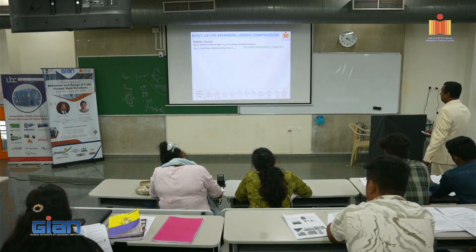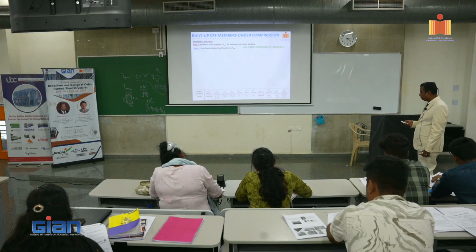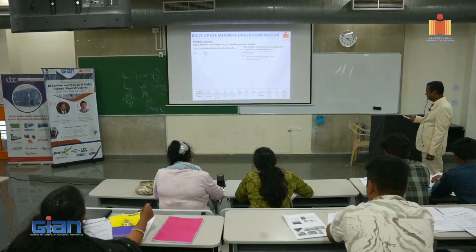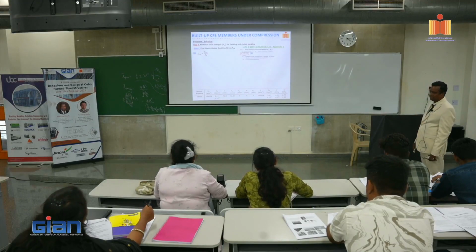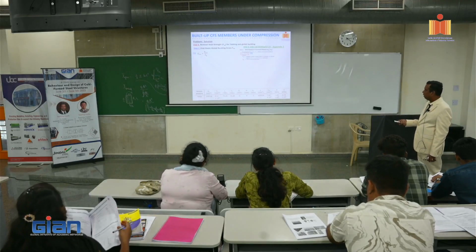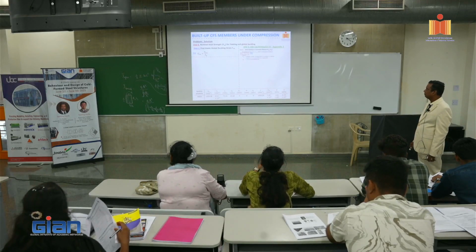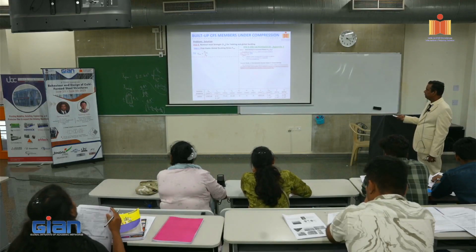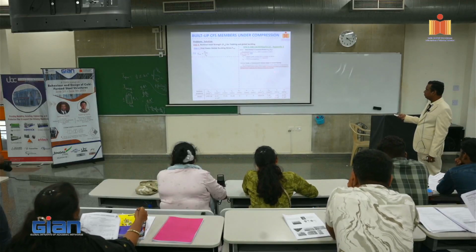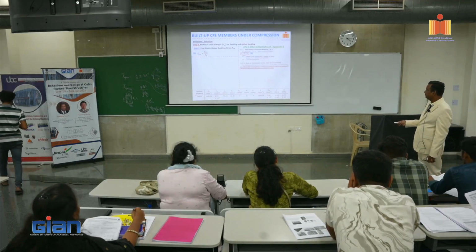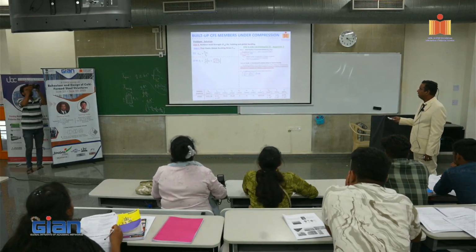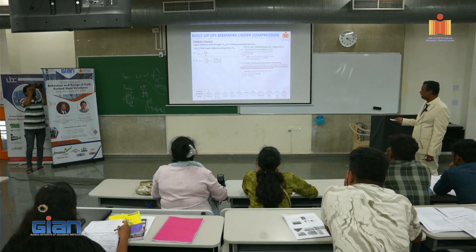So AISI S100 Appendix 2 gives you all these equations. So it says that Fcre, right, is equal to Pcre divided by Ag, right? Very simple. But now how do you calculate Pcre? Pcre shall be taken as the minimum of Pt as designed, including the influence of holes if applicable, right? So now let's calculate Pt. What is Pt? Pt is the torsional buckling load, right?